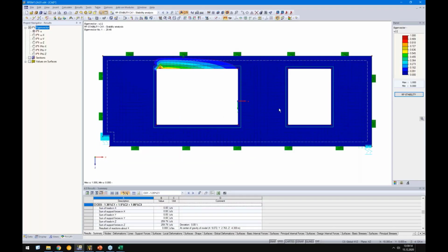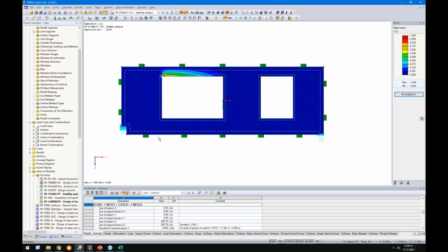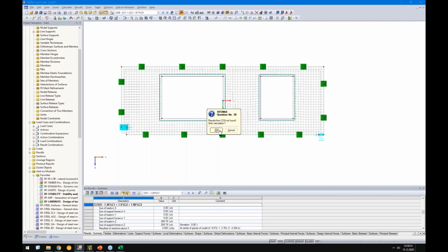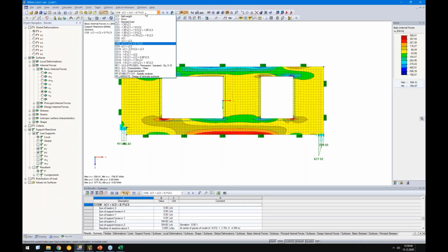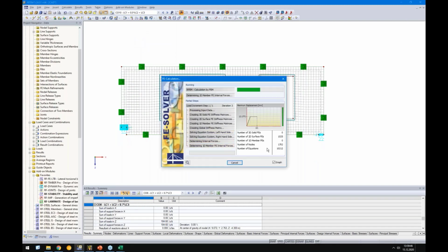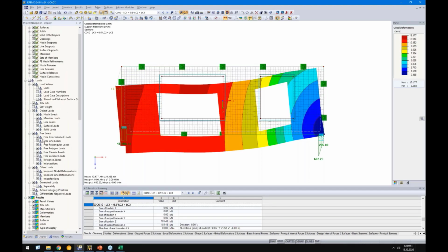Okay, then at the end, there's not much more time anymore, but I will need 5 to 10 minutes more. I will show you this serviceability stuff that I mentioned in the presentation. Okay, so let's check. In this case, let's focus on CO8 only. So CO8, that's the characteristic deformation with snow load, or maybe the other one is more important, because the imposed load was higher than the snow load. Okay, so let's check the deformation of this element.